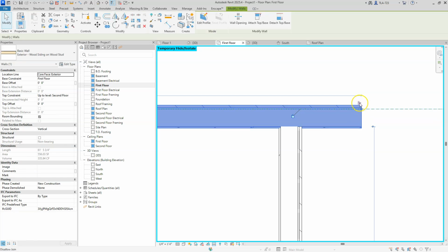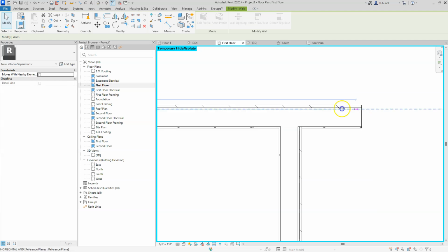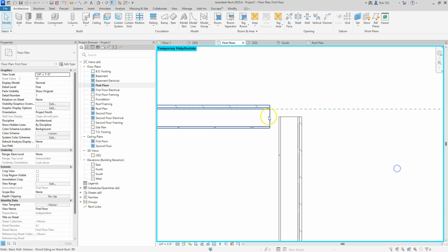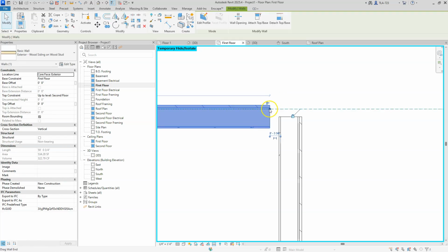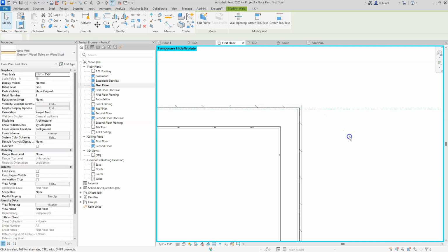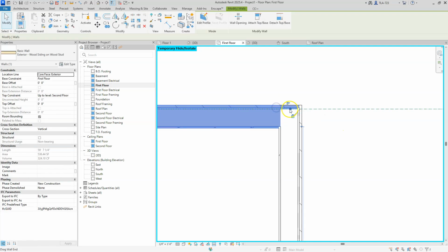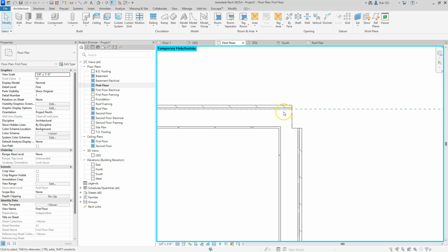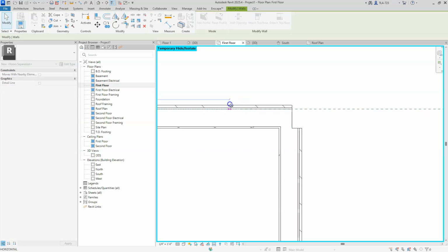We also see there's an icon here that says disallow join. There are certain circumstances, although they're rare, where we don't want a wall to join with another one when we overlap it, right? In this case, I did not disallow the join. Let me try that again. I'm going to disallow that join, and now when I pull it over here, it's still joining. Interesting, okay?